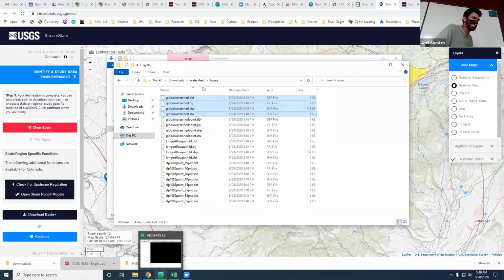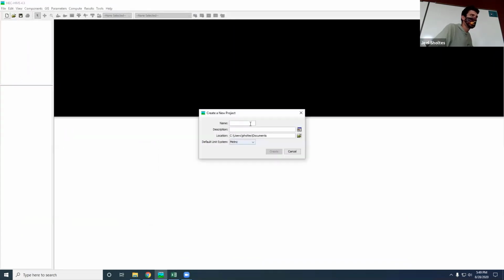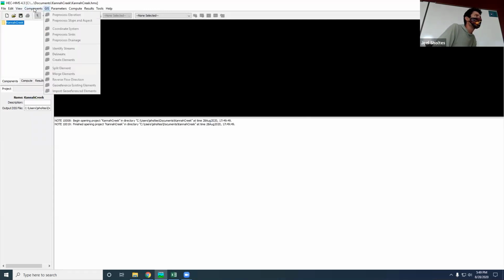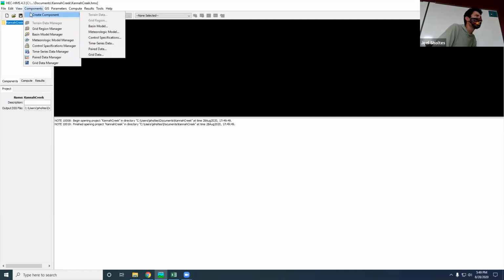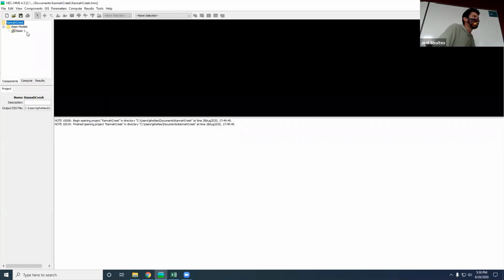So let's do that. We will first open HMS, and we're going to do a new project here. We'll call it Canna. It's going to save it in my documents folder. Let's do US customary for units. We'll create it. And then we'll want to do a new basin model. That's the first thing we'll do, a new basin model. And we can just call it basin 1. We can give it a name either way. So that's the first step, basin model.